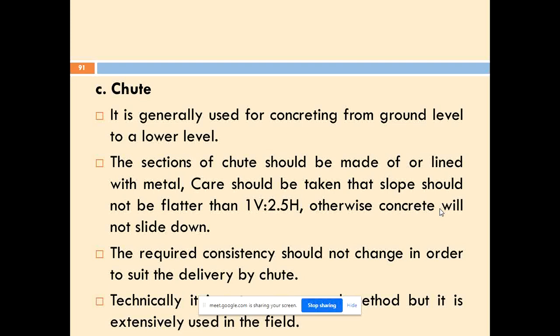So you saw the advantages and disadvantages of the mortar pan as well as the wheelbarrow. You should remember the 4 M's in any of our work. Okay, the 4 M's are men, material, machine, and money. So you know what the labor cost for one day is. The labor cost for one day is quite high nowadays. So if you use a mortar pan, you require a lot of labor, and if you require a lot of labor, then the cost also will go high.